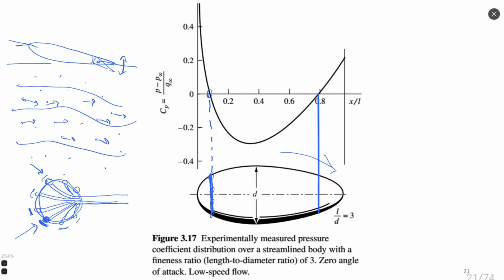Oh, no, it's a minimal, or could be maximum velocity, could be minimal pressure coefficient, sorry. Maybe CP0 would be somewhere here. But depending on structure and depending on the model, I think, we can predict direction of the flow, analyzing distribution of pressure measured on the sphere. Spherical sensors are usually very efficient to understand flow direction and flow velocity.